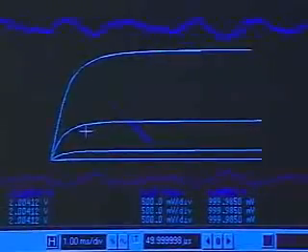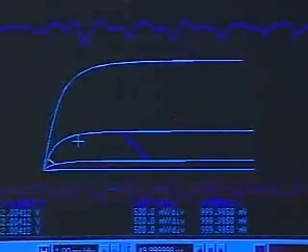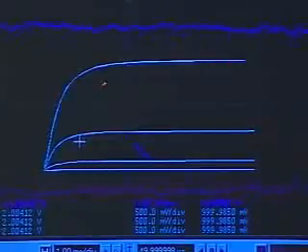So notice that as I went up here, the volume kept increasing because the gain kept increasing. But as I got into the triode region, I began to lose my gain because, remember, the amplifier doesn't have gain in the triode region, when the MOSFET's in its triode region. And we also get a bunch of distortion out there.